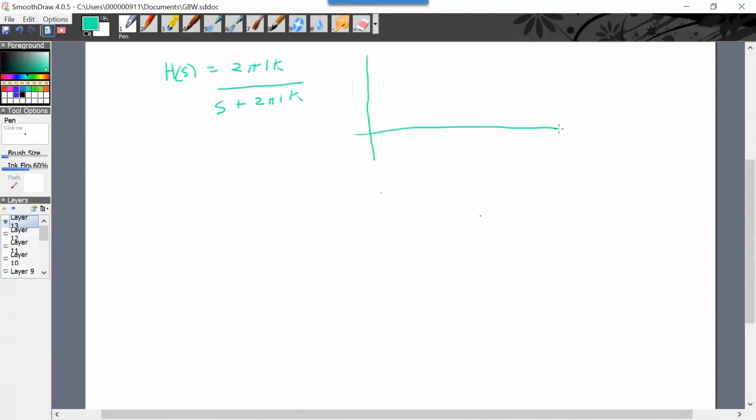So what I can do graphically, right, is say, or even let's give it a gain, right? So that's 20 dB, and this is going to be, the way I've drawn it, 1 kilohertz. All right. So then, yeah, we have an RC filter. And since we're talking about op amps, you really do need that buffer, right? But also we need an op amp, because we need gain.